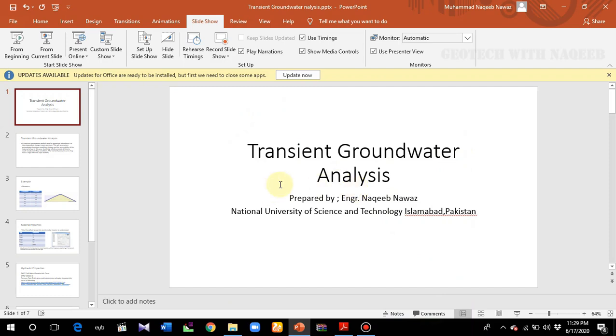Today in this video, we'll be learning about the transient groundwater analysis. Basically, transient groundwater analysis is when we are dealing with pore pressure generation with the passage of time, meaning when we want to analyze how much pore pressure is generated in some particular time. For example, how much pore water pressure is generated in 10 hours, in 50 hours, in 100 hours. This time dependent analysis is basically called transient groundwater analysis.